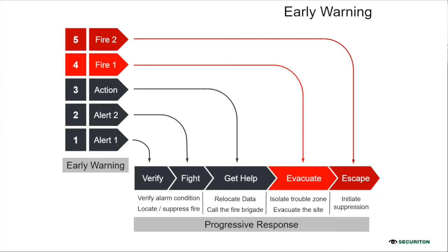Early detection or warning is key for quick and safe evacuation as well. The earlier we detect fire, the less the damage, and maybe no damage if you detect the fire at a very incipient stage. There are different levels available, right from detection to evacuation, in the aspiration detection system. When smoke is detected, you may get different signals. It gives you alerts at different levels of smoke, and when the smoke reaches the threshold, then the fire signal comes.